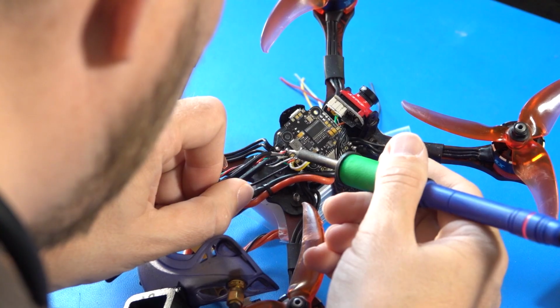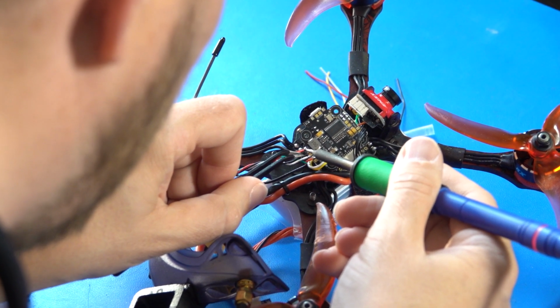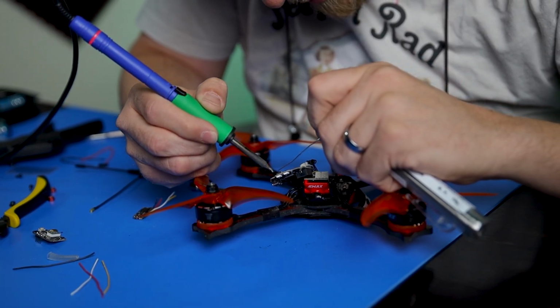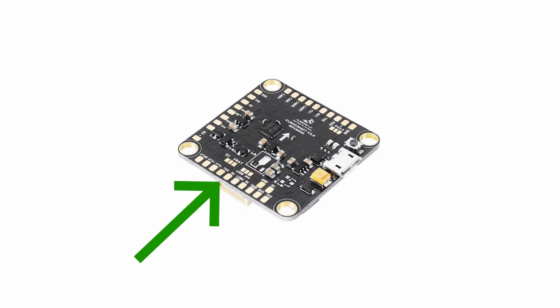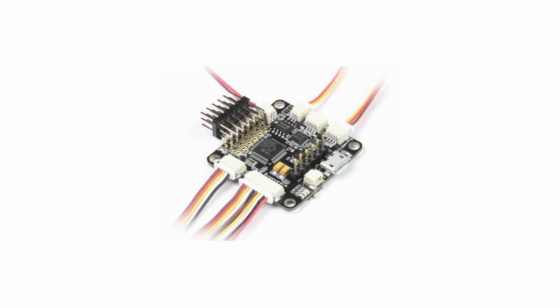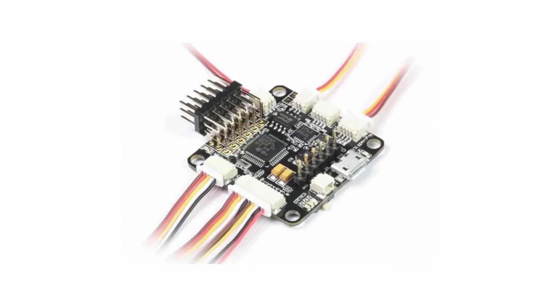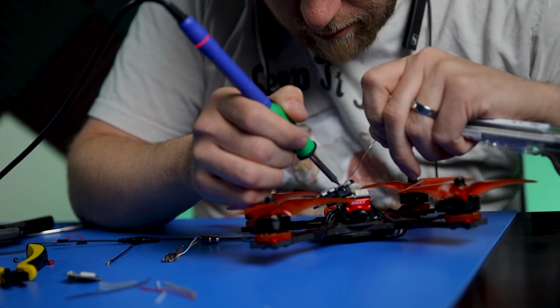Solder pads. During this course, you will learn a lot about soldering, but while we are discussing flight controllers, it is important to get into some of the basics. Because everything stems out from the flight controller, it is important to know what connections or solder pads are available. In some cases, flight controllers may be equipped with connectors so that soldering is not necessary. For example, most flight controllers have the option to connect a 4-in-1 electronic speed controller without soldering. However, for most other components, soldering will be necessary.